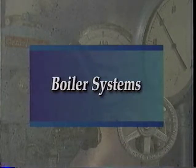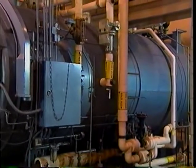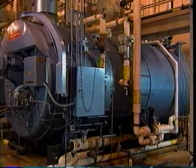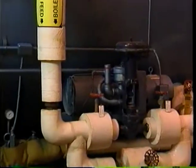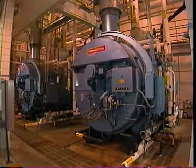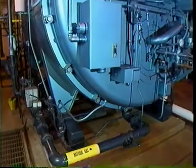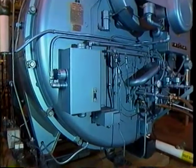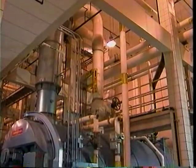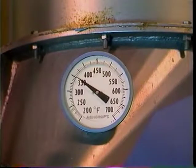Boiler systems. A boiler operates using the feed-water system, the steam system, the fuel system, and the draft system. The feed-water system supplies water to the boiler. The steam system controls and directs the steam produced in the boiler. The fuel system supplies fuel and controls combustion to produce heat. The draft system regulates the movement of air for combustion and evacuates gases of combustion.